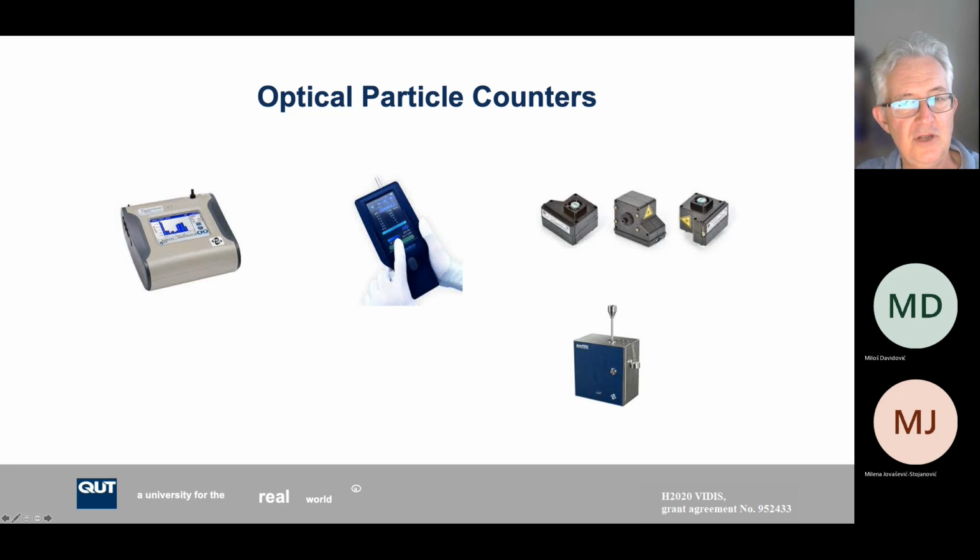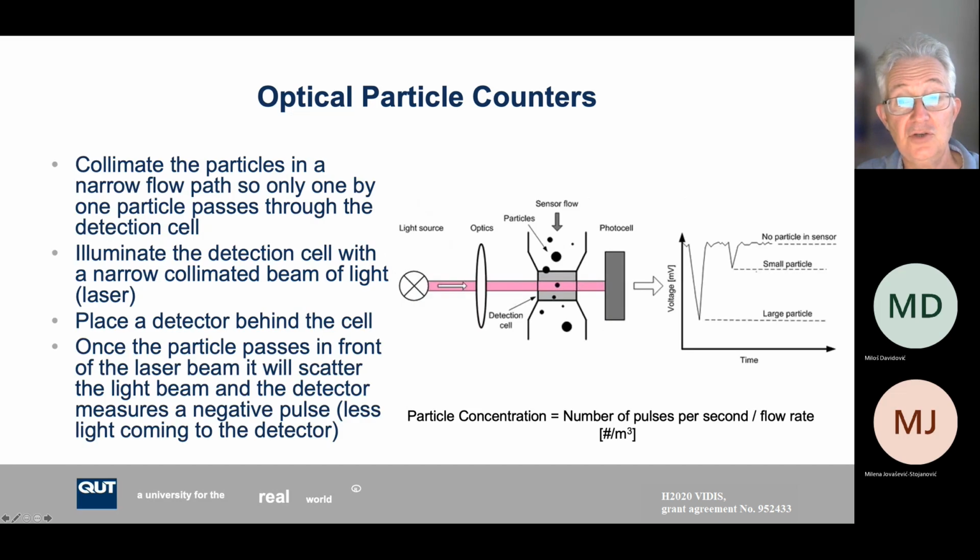So the limitations of particle counters are twofold. There's the limitation on the amount of light the particle scatters. The smaller the particle, the less light it scatters, and if the particle is sufficiently small, it won't scatter any light, or the light will be within the noise. The other limit is on the number of particles, or the concentration, that these counters can handle.